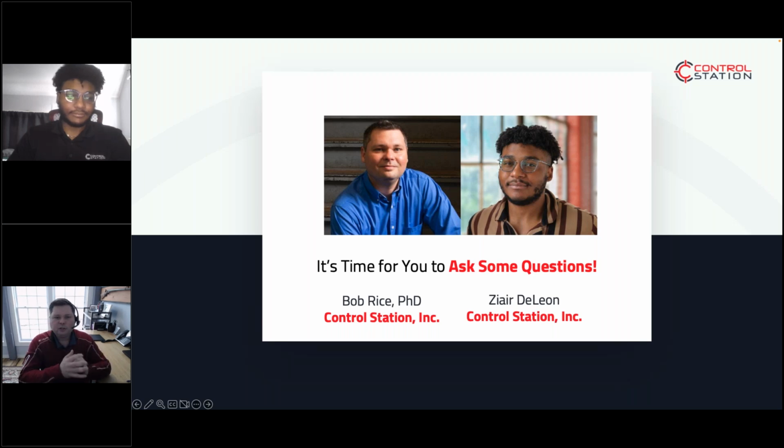Zaire, what is your approach? Yeah, so I agree. The absolute worst thing you could do is just start right off the bat with all the metrics going and trying to figure out IAE and oscillation and output travel and all these different metrics at the same time, right? It's a fire hose of data, and it's going to frankly overwhelm you. It overwhelmed me when I first started doing this because CLPM does produce a lot of data. I'm inclined to agree that operating mode is probably one of the most important things, right? If your PID block isn't running, well, then nothing else is going to frankly matter.